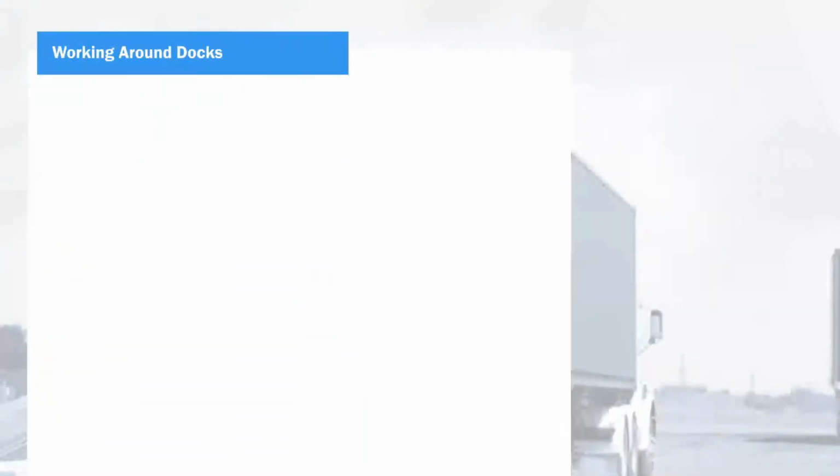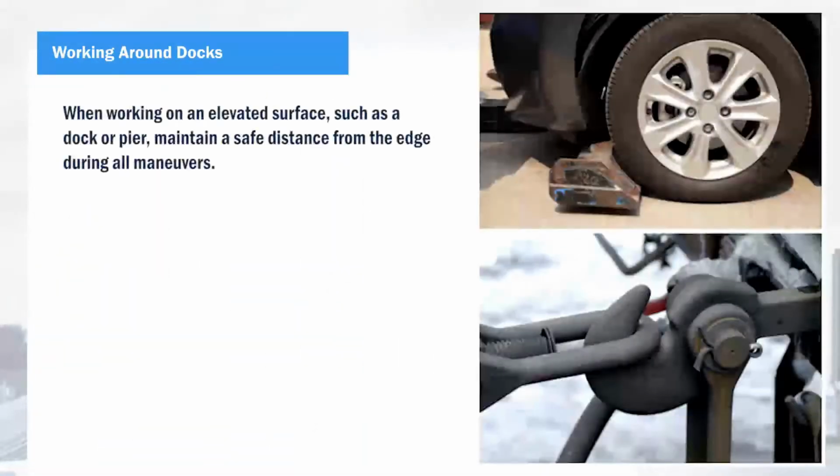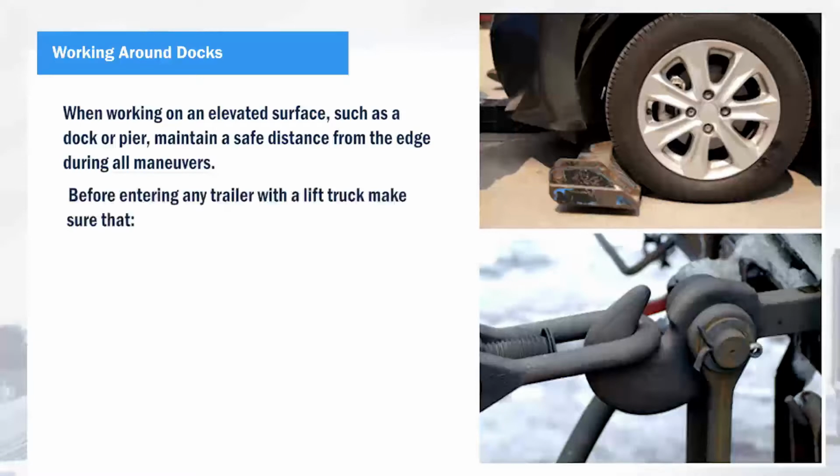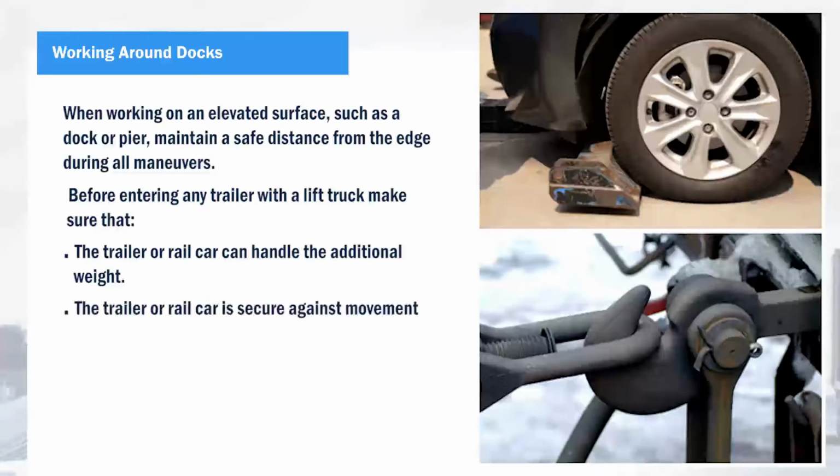Working around docks. When working on an elevated surface such as a dock or pier, maintain a safe distance from the edge during all maneuvers. Before entering any trailer with a lift truck, make sure that the trailer or rail car can handle the additional weight. The trailer or rail car is secure against movement.